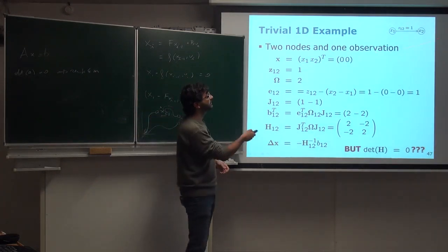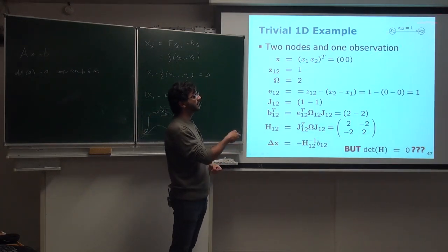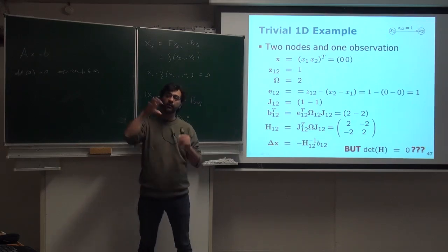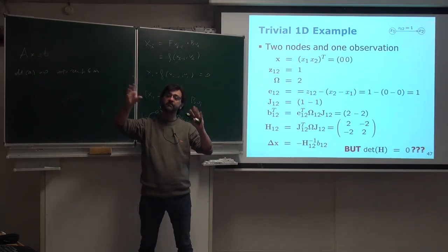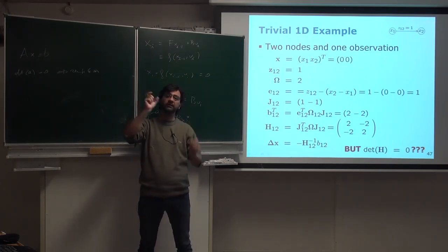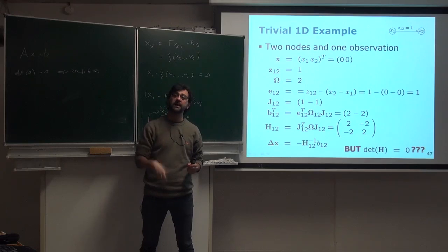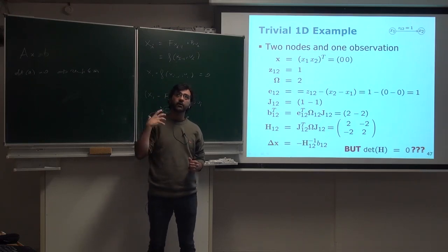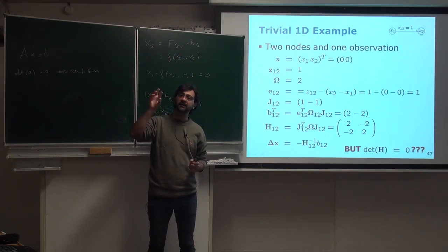We only have relative measurements, not only in this case, but in the generic pose graph or graph-based SLAM. We always think about measurements between nodes, so relations between pairwise nodes. But we don't have any global measurement that tells us this specific pose is at this specific location.